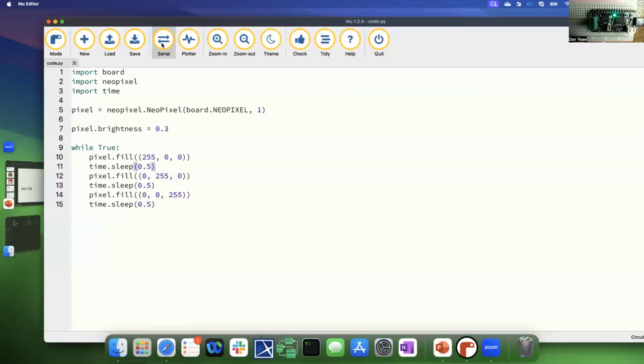We could, of course, combine these and flash the LED and the NeoPixel or something like that. I know those are all pretty straightforward examples, but I think they're useful for showing how you load a library, how you get parts of the device using board dot the device name, and create a while true loop and start interacting with the device. That's pretty much what I wanted to go through for the demo. Are there any questions about any of that?